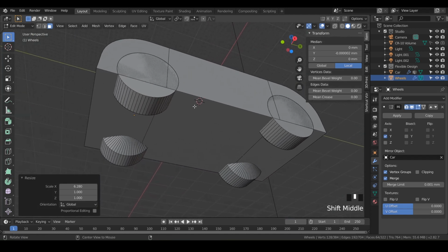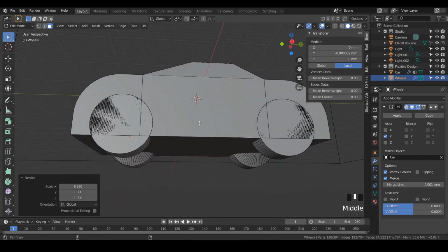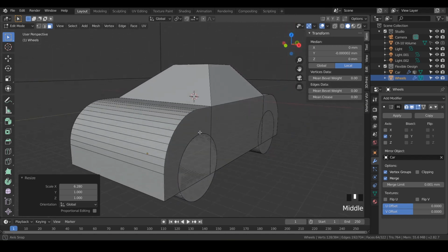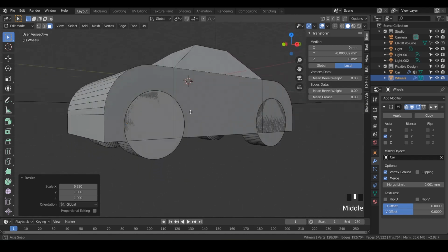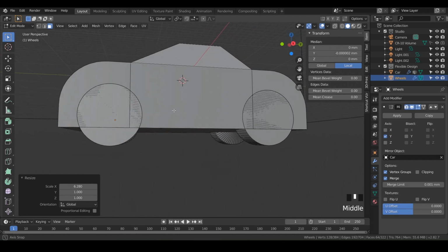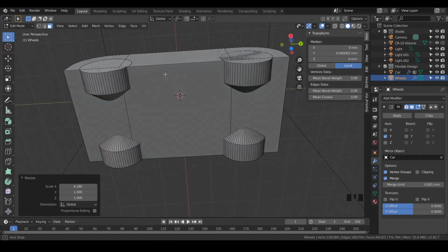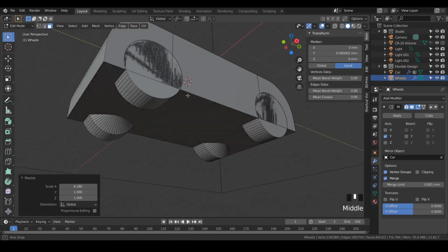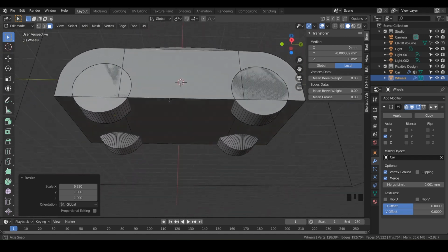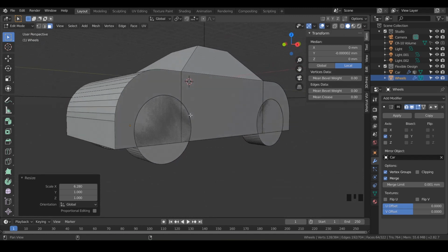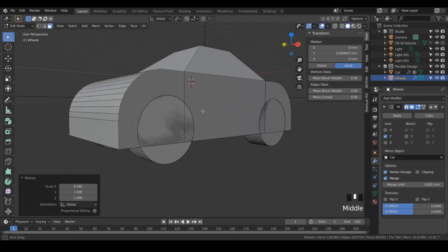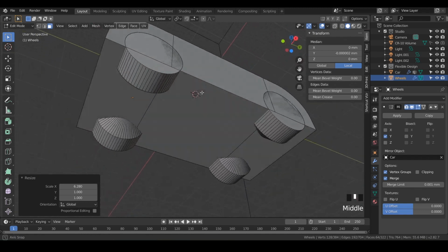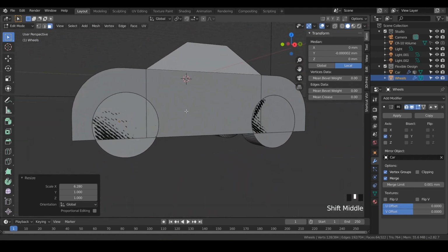So I found this really cool trick inside of Blender to do offsets or tolerances. If you're not familiar with tolerances, that's just the tiny gaps in between two separate parts that will essentially let these wheels roll on their own. It's a very, very important skill to know tolerances in 3D print design. So I'm going to show you some tips and tricks that I use all the time so that you know for sure that you've got the right amount of clearance for your tolerances.